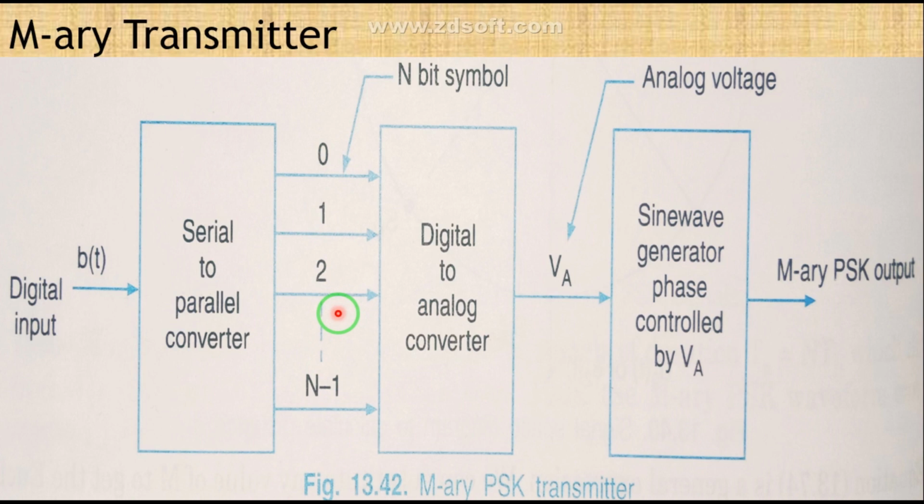It is the time required for this converter to assemble a new group of n bits, right? So every n Tb seconds, after every symbol duration, the converter output is updated. Since these n bits per symbol are present at the output for a duration of n Tb, after n Tb you would get the new input and the new output would be updated at the output of this converter block.